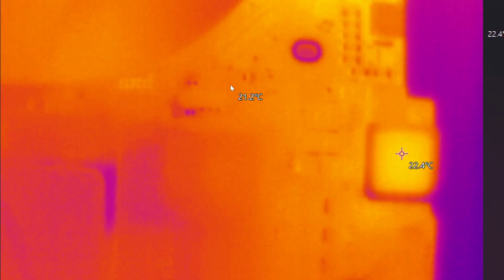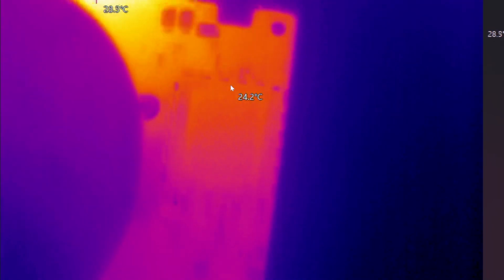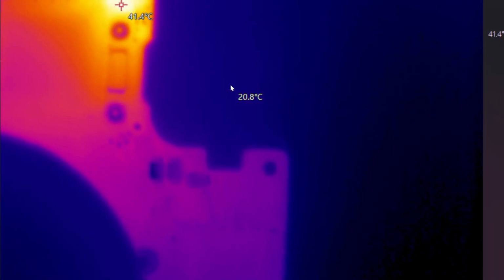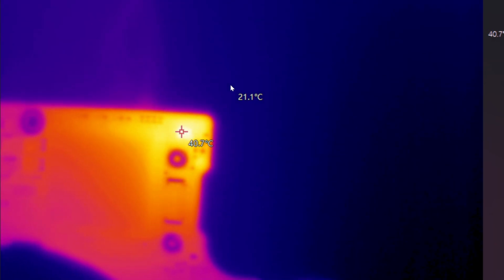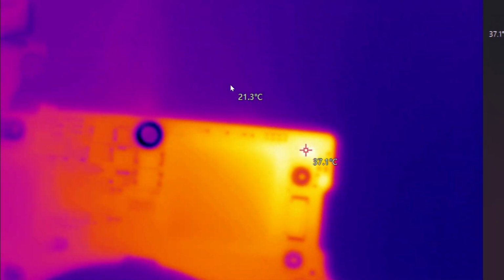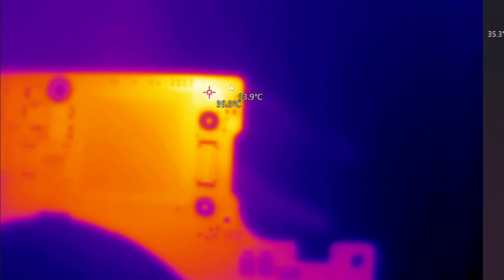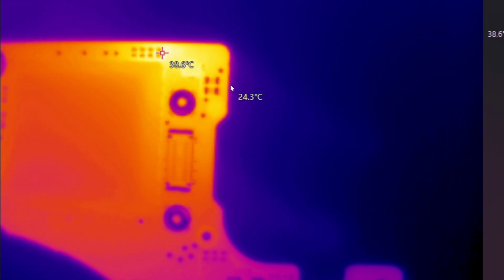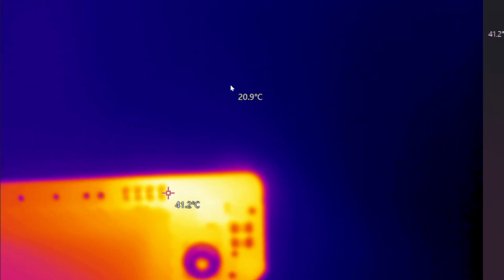Normal heat from our PP Bus G3 hot coil. Those will get hot. That's why they have a thermal sticker on them. Oh, that doesn't look right. So that stands out. Okay, but if we look at this, it doesn't really look like it's coming from this side of the board. So we could zoom in here. We're just going to zoom in really close.